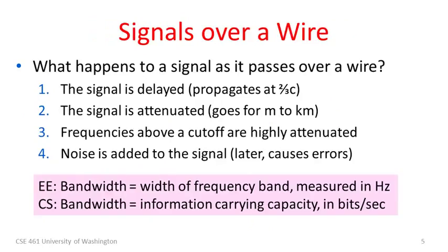Okay, so this last bit that we learned, that fewer frequencies degrade the signal by making it transition less rapidly and getting more rounded, is key to understanding what happens to signals as they pass over a wire. In fact, I can now tell you that there are roughly 4 effects that happen as the signal propagates across a wire. First of all, it's delayed because it takes a little while for the signal to propagate, as we heard before, so a fraction of time will pass.